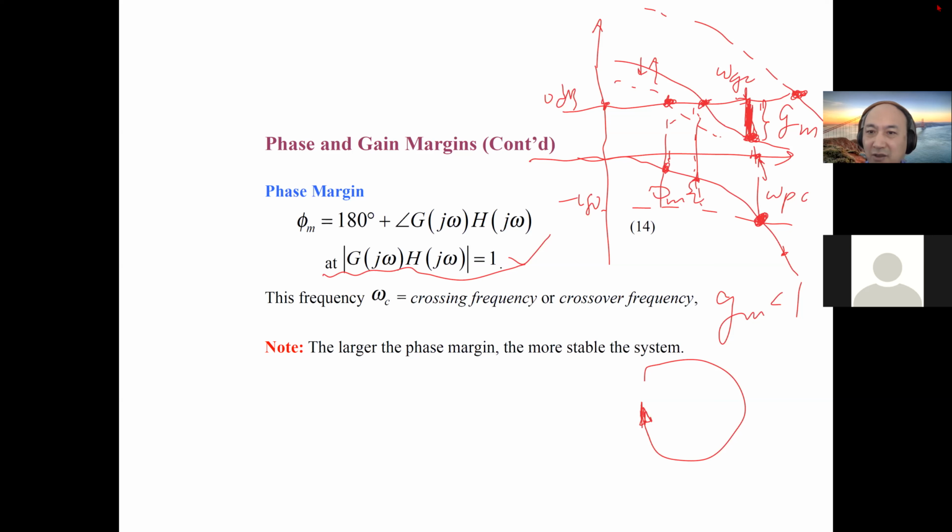So you can see that while I cross over, because I increase the gain, my phase will not change, okay? So you can see crossover 180, then this is greater than 0. So that means I have something come over here. This is greater than this, and when I add it, remember it's negative feedback, so you have a 180. Then this gets amplified until you explode. So it's unstable. If you increase the gain to here, this system is unstable, because you cross over here, beyond 180.